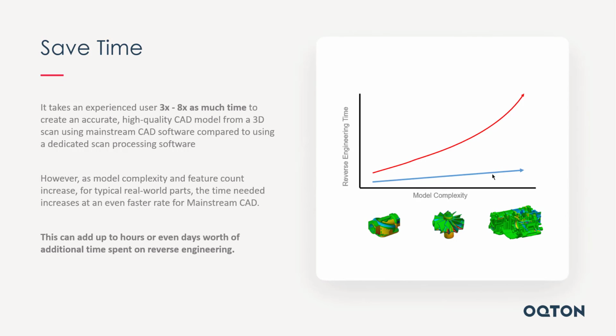So finally, I'll get a lot of people asking me, look at my parts. Do I really need a 3D scanner and software like this to reverse engineer my parts, right? Sometimes there are people that have an application that's kind of right on the line, right? And this is kind of where I go with that question: how complex is that part? If it's just a 1, 2, 3 block, obviously I can measure that with a pair of calipers and model it in CAD faster than I could even unpack my scanner. But as the complexity increases, the more time you're going to save.